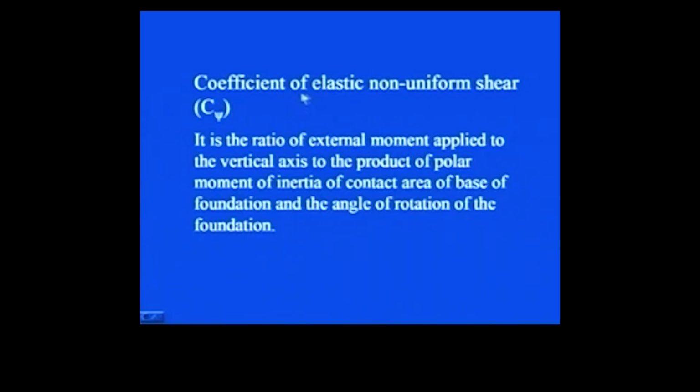Third one is coefficient of elastic non-uniform shear. We represent it as C psi. It is the ratio of external moment applied to the vertical axis to the product of polar moment of inertia of contact area of base of foundation and angle of rotation of the foundation.